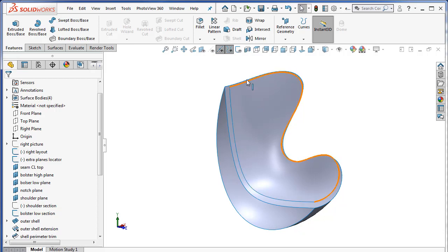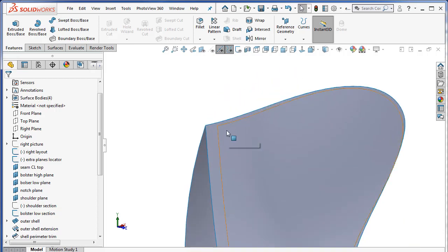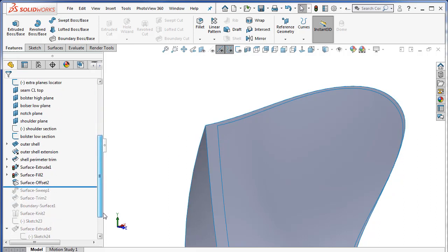For example, when building the egg chair or the womb chair, this offset surface needs to be trimmed back a certain distance and a new transitional surface built that will go from the trimmed back surface back to the seam edge to give the impression of a puffy, stuffed, cushiony chair.